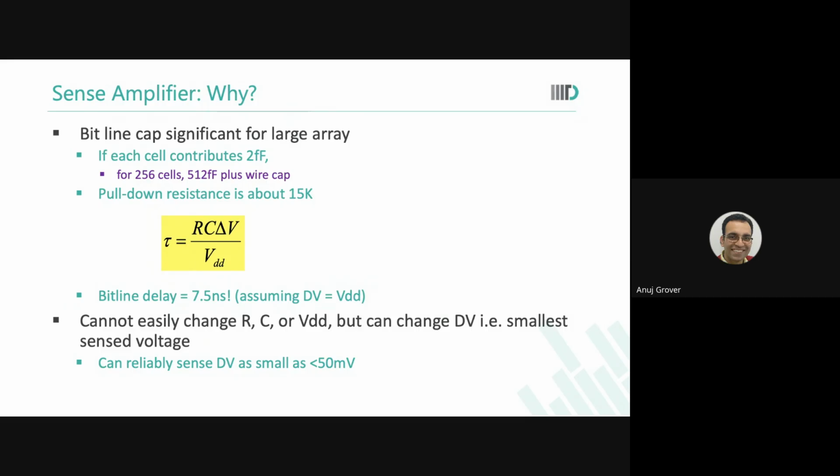So I use an 8T cell with bigger devices on the read port so that I can read very, very fast, through an inverter. A typical one read, one write cell in any given technology would have at least 30% more area than the 6T cell. In an 8T cell, you have a 6T cell plus 2 extra transistors which discharge the read bit line. That is typically 30% extra area. It can be 35, can be 45 also, but 30 is what technology generally offers in a vanilla flavor. If you want more speed, they will go to a larger cell also, but vanilla is 30% extra area.